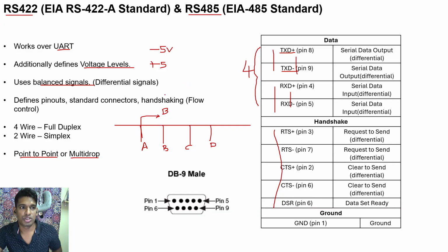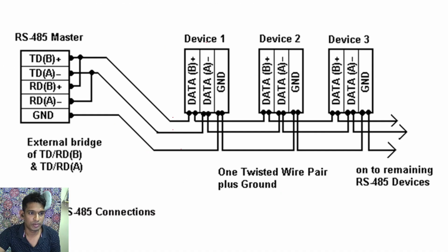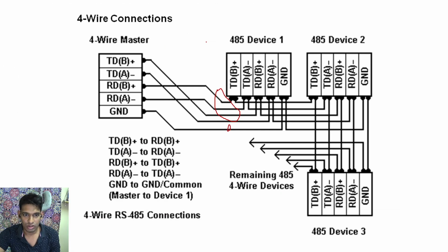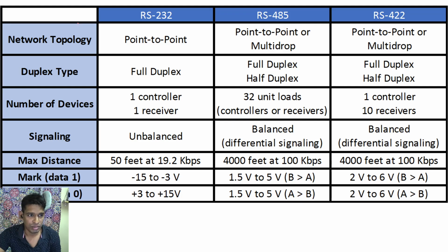So that is what you should keep in mind when using these devices to communicate with relays, or with SEM meters, or with any other Modbus devices, or when you're using these devices in an RTU network, or in a SCADA network. Basically, you're using multiple devices at the same time, so you'll most probably be using RS485 rather than RS232. That is what you have to keep in mind. So this is the configuration. This is a summary of the thing.